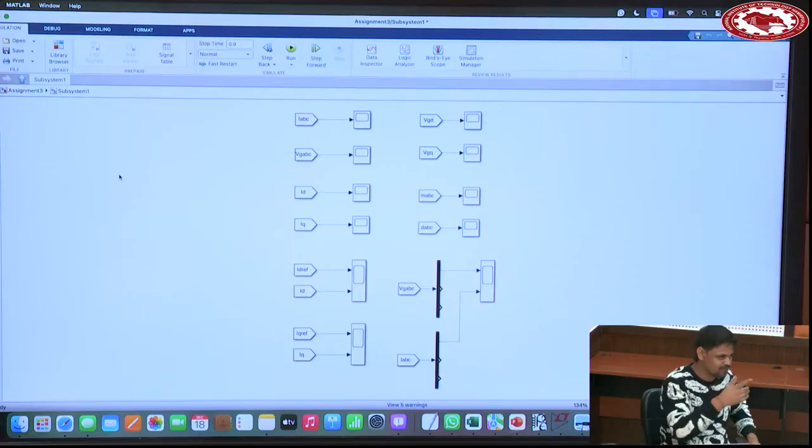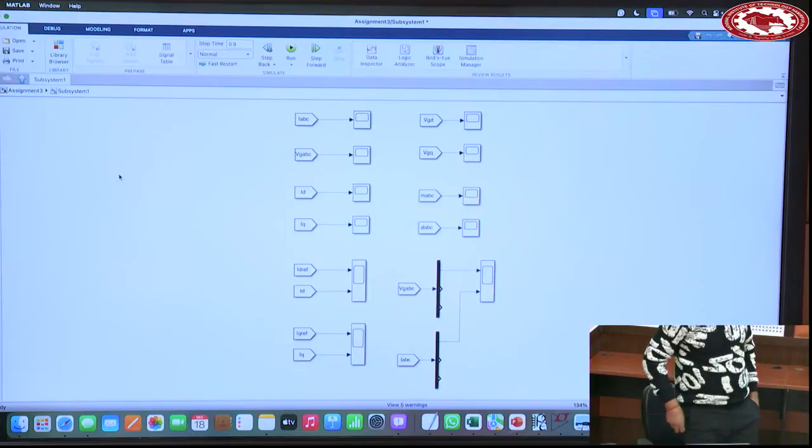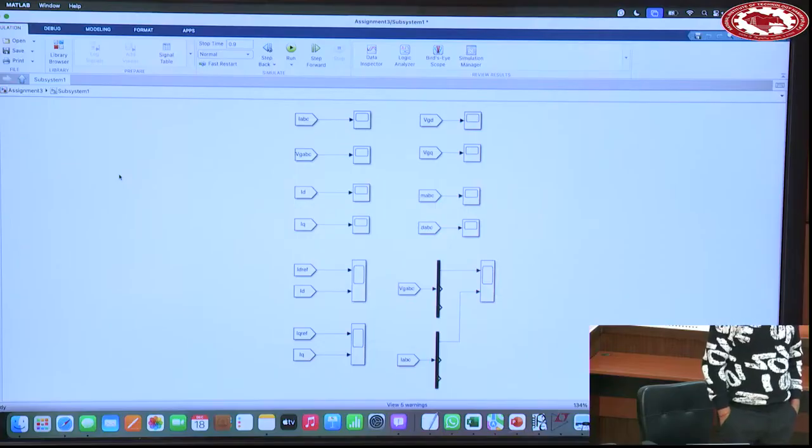One real life example: generally inverters installed at a solar power plant are asked to feed some reactive power in the night time because converters are free, there is no solar. The structure of a STATCOM, grid connected inverter and active power filter is the same: inverter, filter, grid.